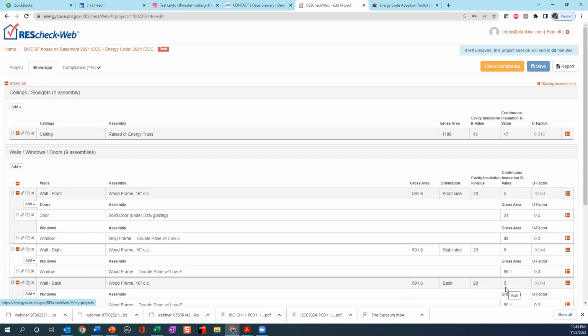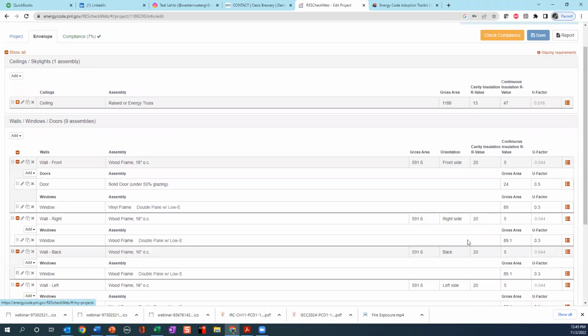So I'm going to trade off what I think is the builder's greatest desire here. I'm going to trade off the R20 wall because 20 wall plus 5 continuous insulation. So really what I'm going to trade off is the R5 insulation, because a lot of builders now are using R23 blown fiberglass 2x6 walls.